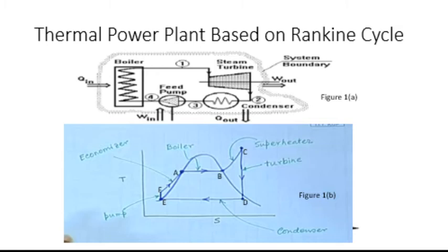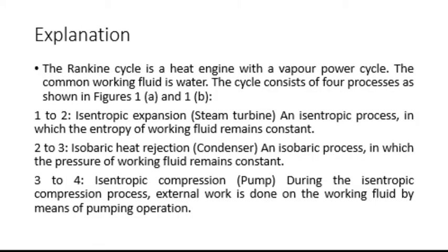Coming back to the 3 to 4 path. In the 3 to 4 path, it is an isentropic compression. During the isentropic compression process, external work is done on the working fluid by means of a pumping operation.